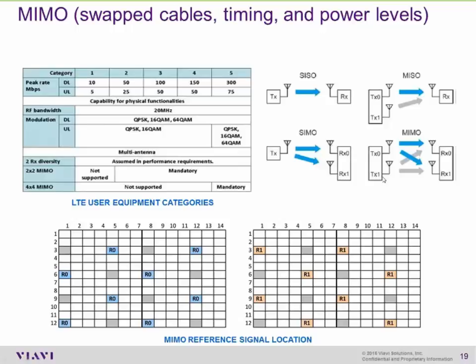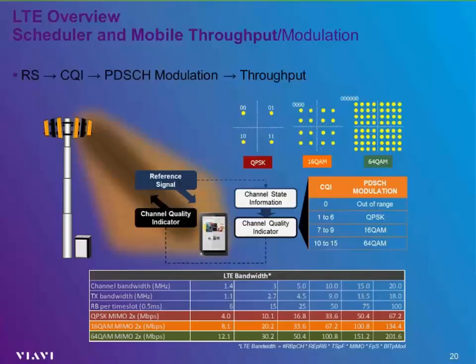I was actually in Puerto Rico. They had a mall that they couldn't get the LTE to work because they were using an existing DAS system, and they came to find out, or I came to point out to them, that they had dummied off the first transmit, which means that they were transmitting into the mall the second transmit with no identity. And all they had to do was swap the cables, and in 30 minutes we had the problem fixed, and they'd been spending weeks trying to figure out what was wrong. So great use of signal analysis.